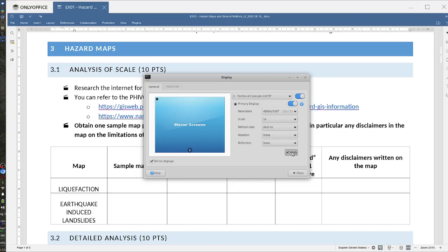We still use deterministic for small projects, and we also use it to check the results of probabilistic analysis. Probabilistic analysis is a very complicated computation. If you just miss one calculation, you can mess up the whole calculation. So it's also important to have deterministic analysis, so you can have a rough estimate of what the numbers should be.